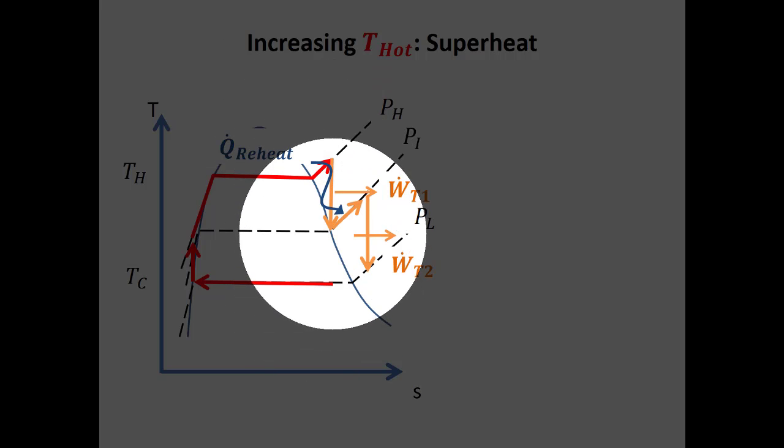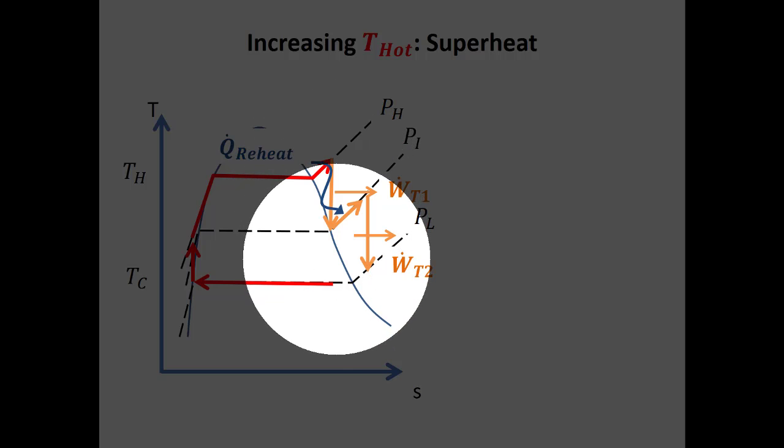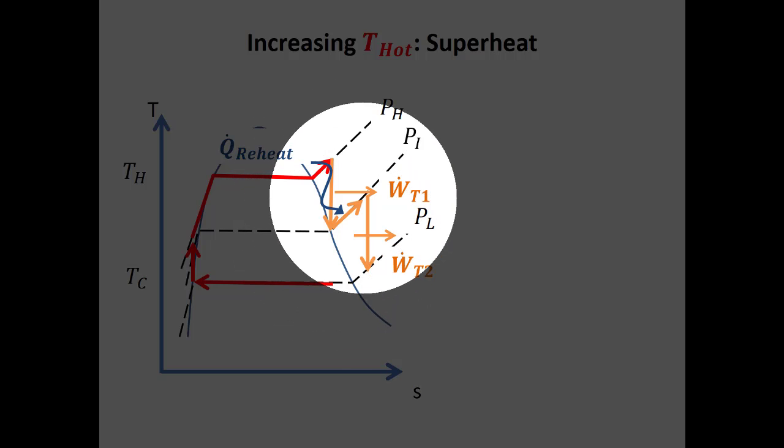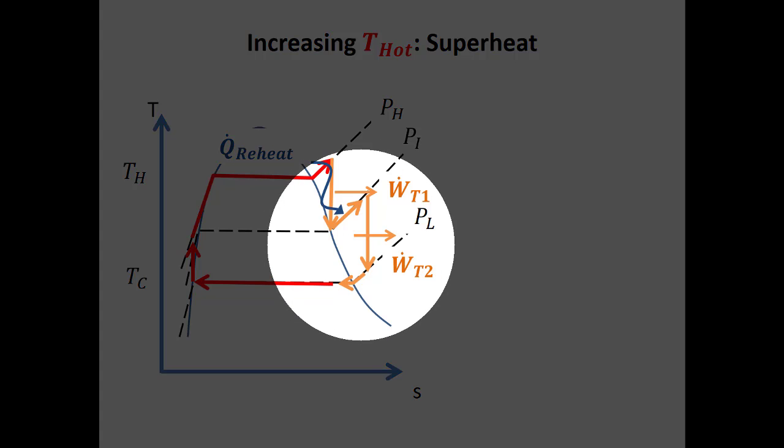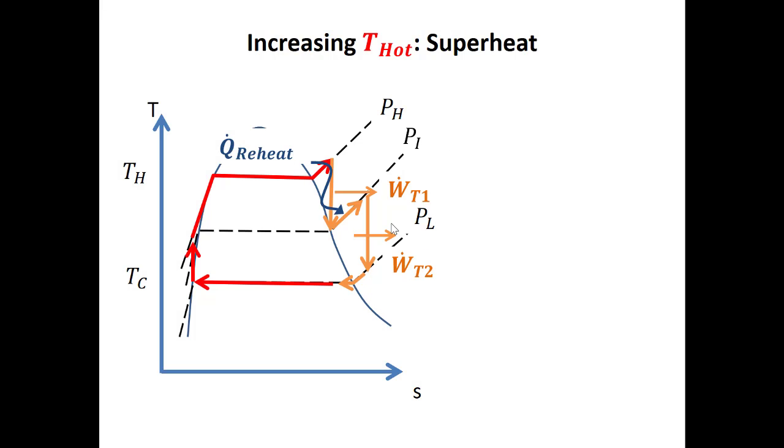So a normal Rankine cycle is almost like having these high and low pressure turbines without this reheat at the intermediate pressure. So when I do this, I'm increasing the amount of work that I'm getting out of my turbines, but I'm also adding more heat because I've got this reheat part. Now, this might sound a little bit weird, but if I'm going to forget something in the analysis, it's this second heat part. So remember that this is called a reheat cycle, or a Rankine reheat cycle. So we're reheating. Remember there's two places where we're adding heat in this cycle.